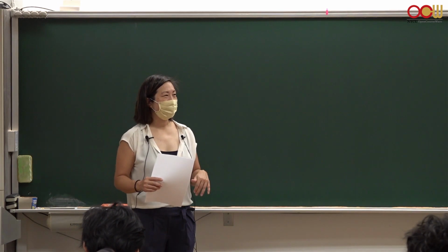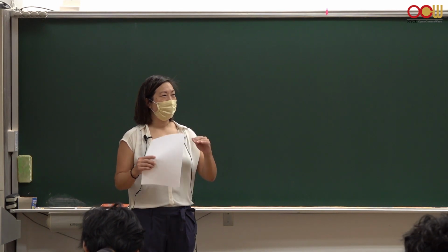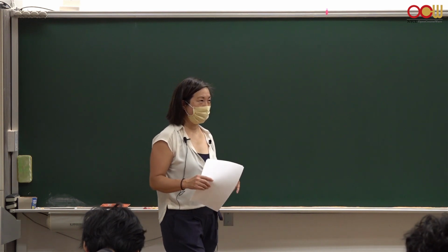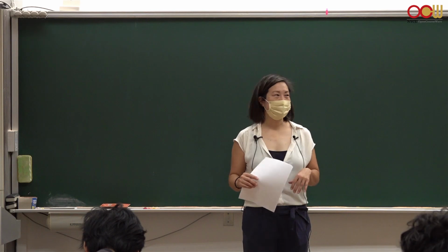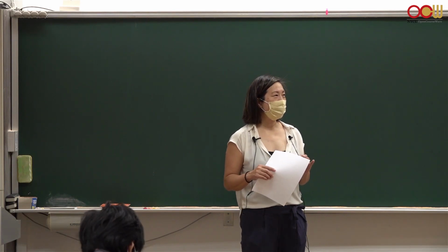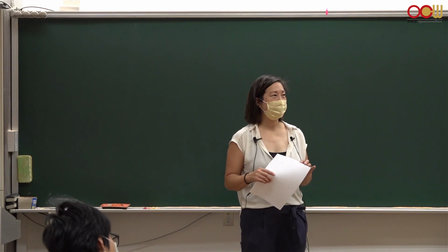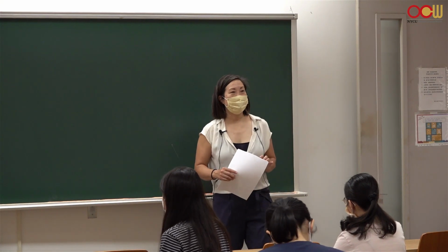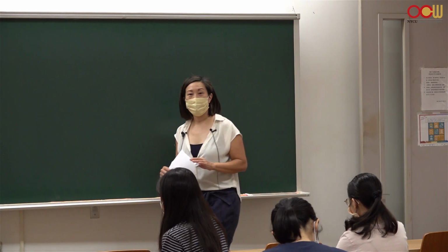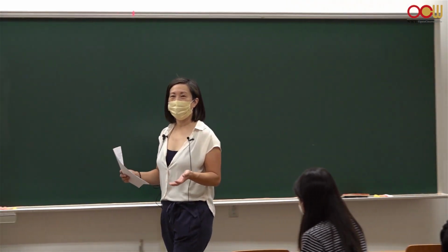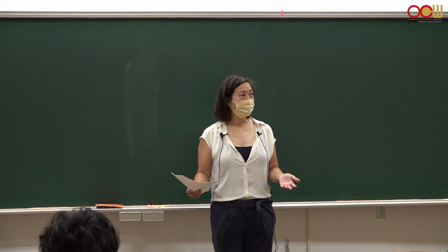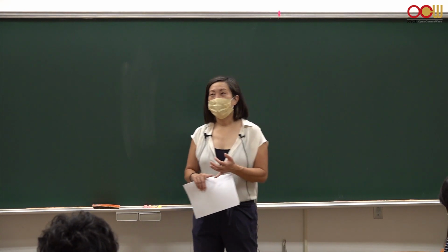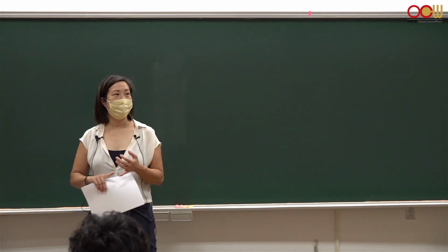How does plastic deformation occur? So we know that plastic deformation is useful to prevent crack propagation, but what is plastic deformation? What happens in a material that allows for plastic deformation to happen? Perfect. Yes, the breaking and reforming of bonds. Another way to look at it or talk about it is slip or dislocation movement, right? And so because of slip, materials are able to deform plastically.